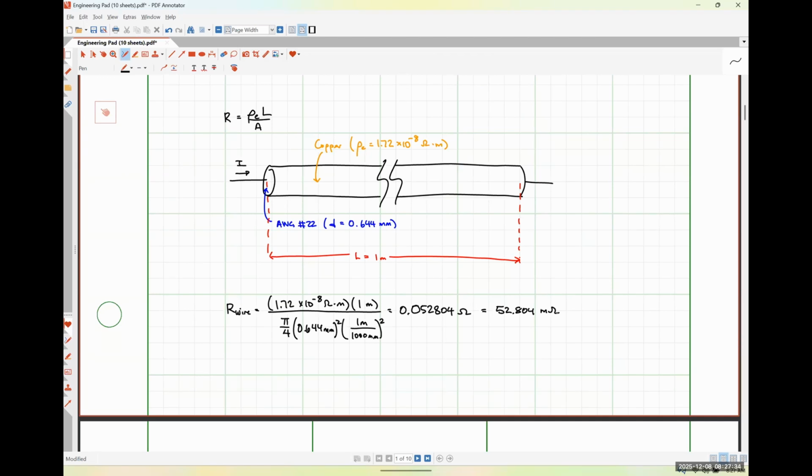Okay. So how does 200 ohms compare to this? Well, let me just do 200, or actually 220, divided by answer. It's 4,000 times larger. So if the smallest resistor that we've ever used is 4,000 times larger than the resistance of a 1 meter long section of wire, which is 10 times longer than any wire that we've ever used, this is a pretty good reason why we get to assume that wires have no resistance.